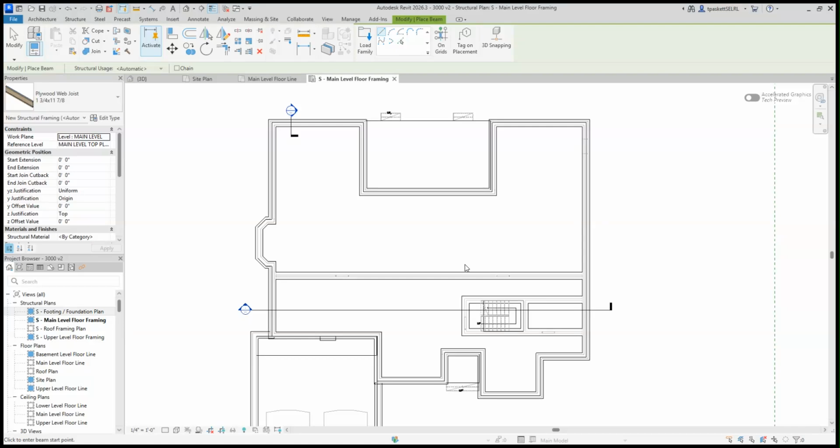And that's really what I want to shoot for, is to go 16 inches on center, 19.4, and design it for that route. That's going to give me my strongest floor and make things work. So there's my sizing. 16 inches on center, 19.4 is my span, and I need a series 210 with an 11 7/8. All right, let's go back to the other sheet again.